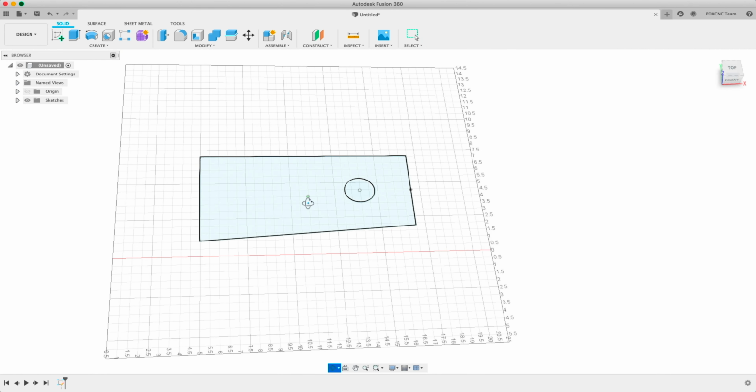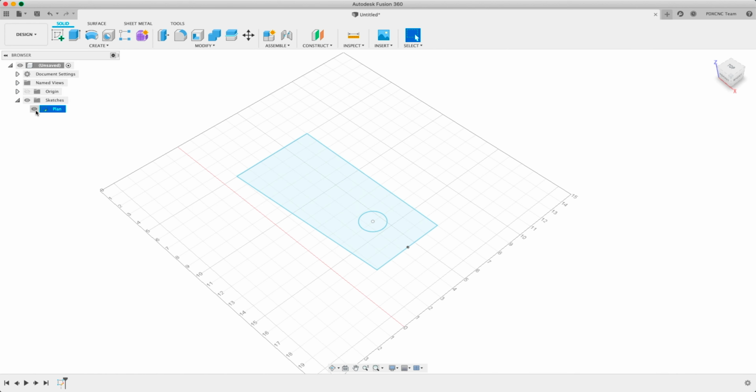And we'll see it in this view. It's just back into the design workspace outside of the sketch mode. So you can see down here, we've now got a sketch that's set up down in our timeline. And it's also in the browser here. So that's sketch 1. I like to change these names right away. So I just click twice, click once, click twice. And we're going to call that the plan. So I can turn that on and off with this little eyeball.